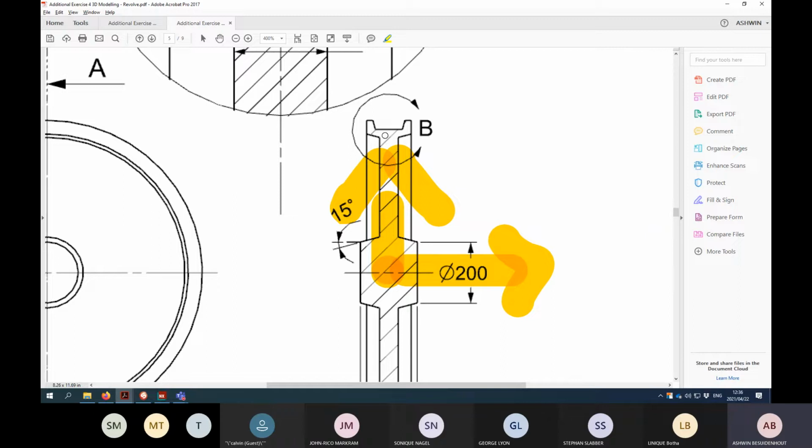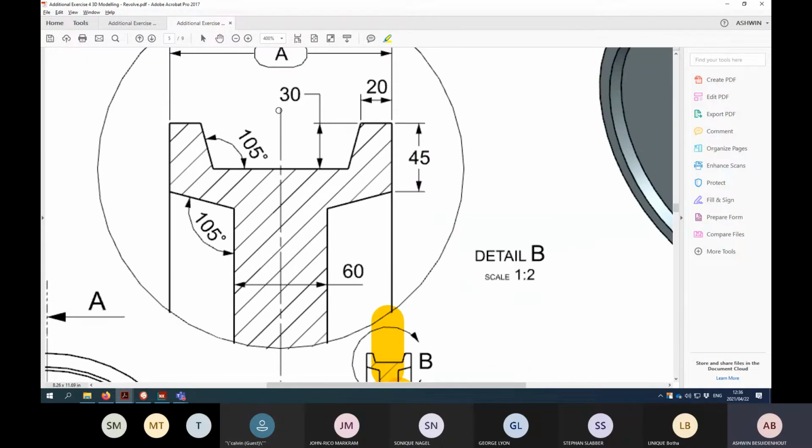Only the section that has been hatched, with these type B lines that show that's being used for hatching, and that indicates material. No hatching there indicates no material, so that's a void. So of course you just draw that, but you just draw half of it because this thing is symmetric. Here we can see again a type G line showing that it's a geometric thing, and then you can just draw half of it and work from there.